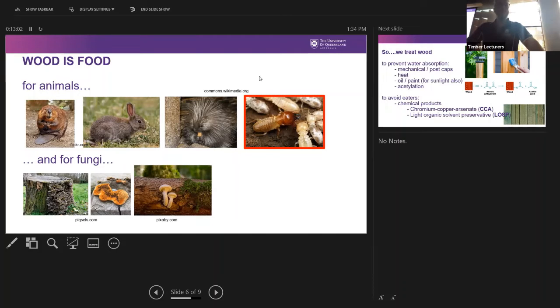And also the most problematic thing with fungi is that when you see that the timber or the wood is rot, it's too late. Because I don't know how much you remember from biology, but the fungi have these three stages: the spores, then the filaments where you cannot see actually anything, and then what you can actually see from the fungi, and that's too late.